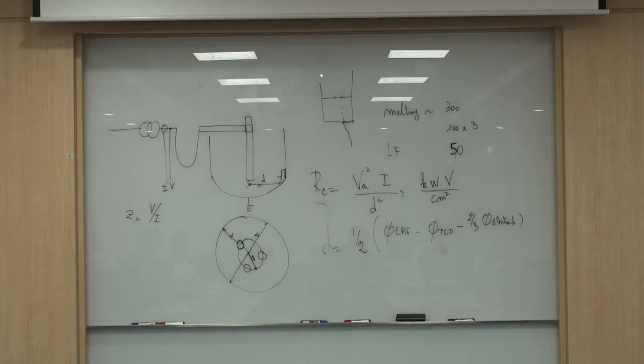How to calculate the diameter of the EAF? It's depending on the volume of scrap only. And we make a diameter and we define the small d. The EAF diameter is only scrap and top weight related. Top weight and scrap weight.